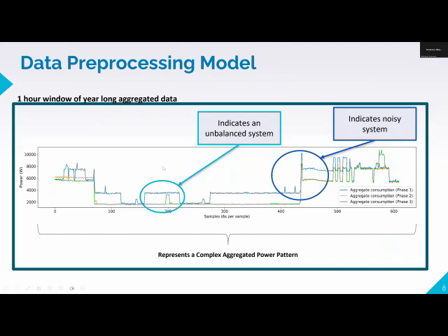Now we recorded the three-phase data. You can see three phases: orange is one phase, green is one phase, and blue is the other phase. The blue has some single phase appliances added to one phase, due to that this is unbalanced. Now our task is, this is the total power consumption, and we need to identify where the other devices are turned on.